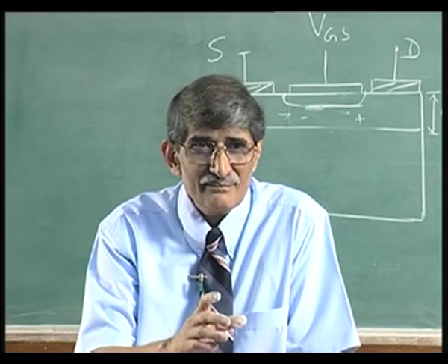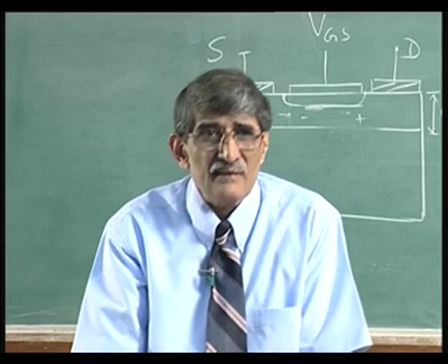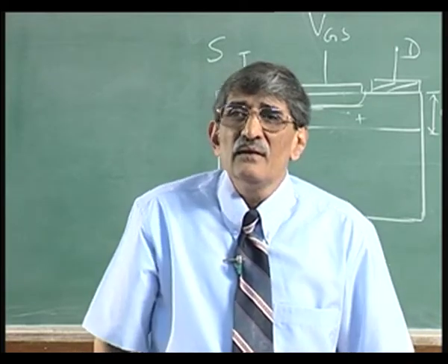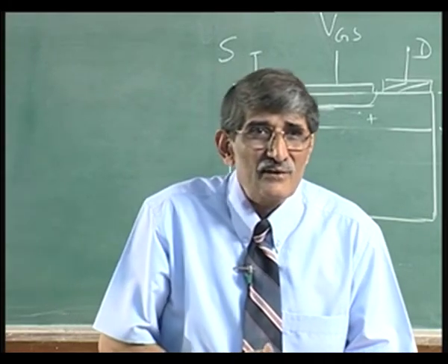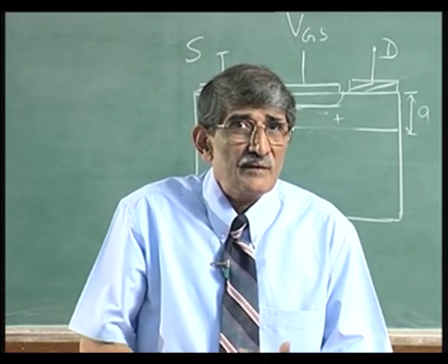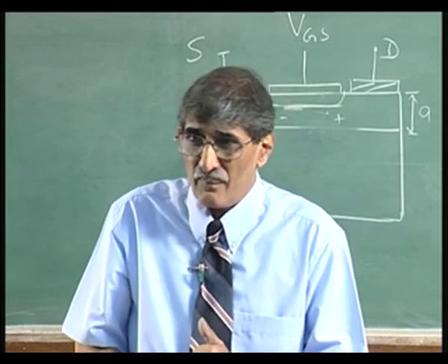They coincide. The velocity saturation and pinch off coincide. That is why Shockley's theory survived so long, because we are talking of channel lengths which are long or pinch off voltages which are small.